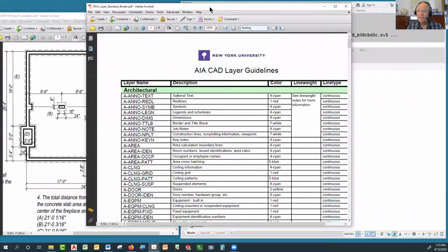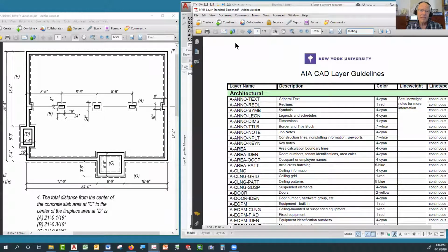What I'm going to do is go through one of the assignments from the class and show you how I would set up beforehand, because I don't want you doing these drawings until you have set up a drawing with all the appropriate layers, blocks in some cases, and settings for dimension styles. Then you're going to use that as a basis for creating a template file, which means that's something you can use anytime you do another drawing that is architectural.